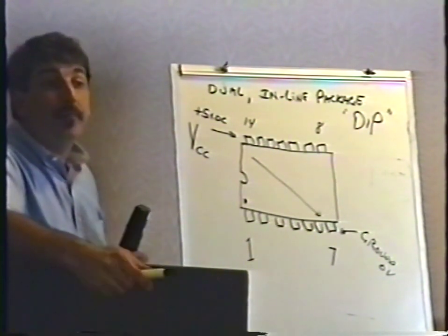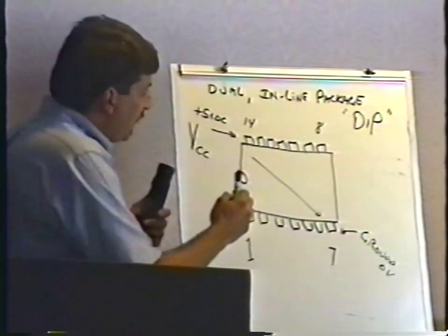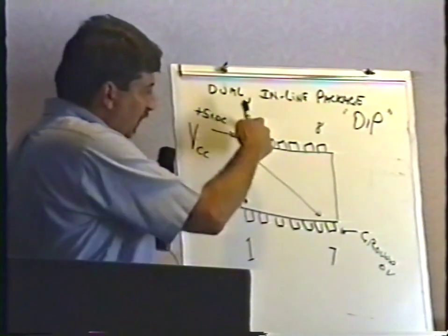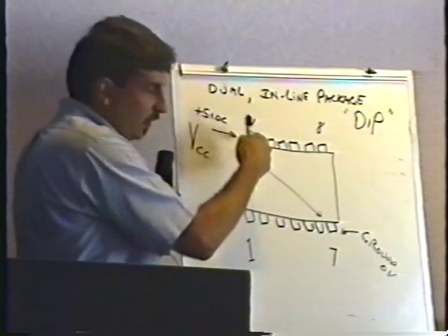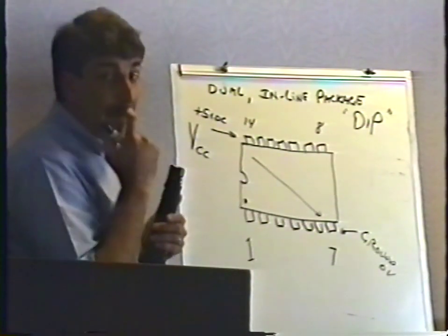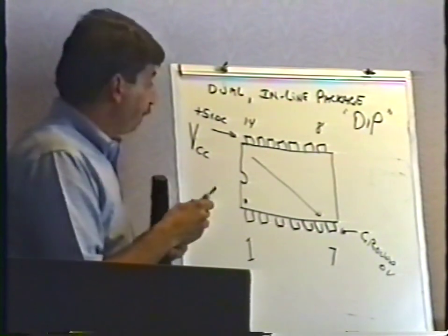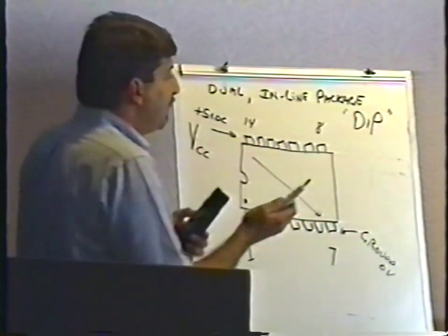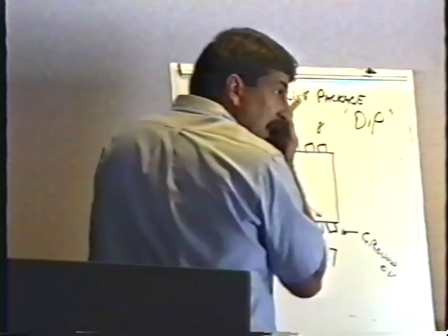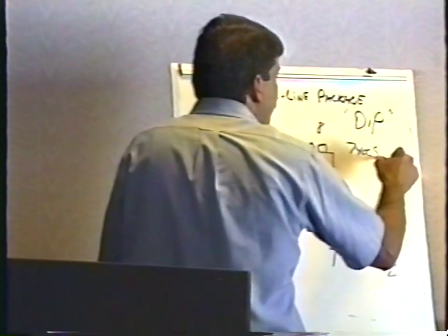Basically, the power is always opposite the dot. The 5 volts is always right above the notch. Holding the notch to your left, it's always right above there, or almost always. Now, specifically, there is one type of integrated circuit that I do look for. We have a family of integrated circuits that we use in games, and it's known as the 7400 series.